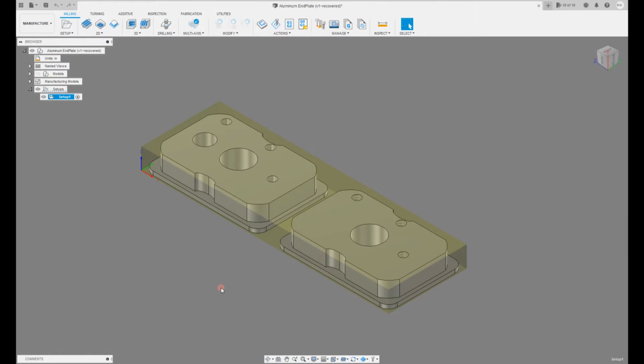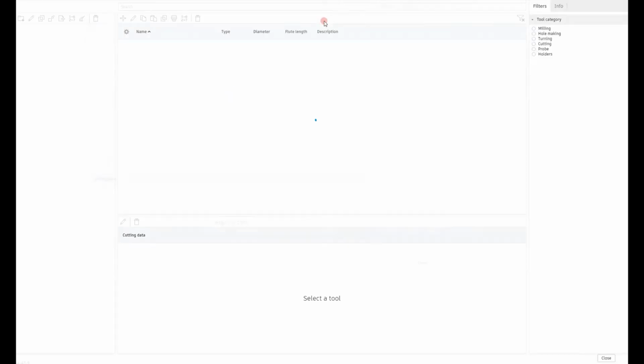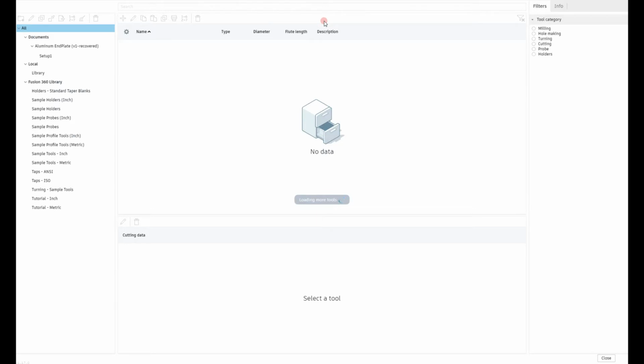features that I use pretty often. First off, the tool table. I use my tool table a lot for two reasons. First, in Linux CNC, I keep it updated to match my library in Fusion 360. Primary reason for doing this is my tool change setup on my router.